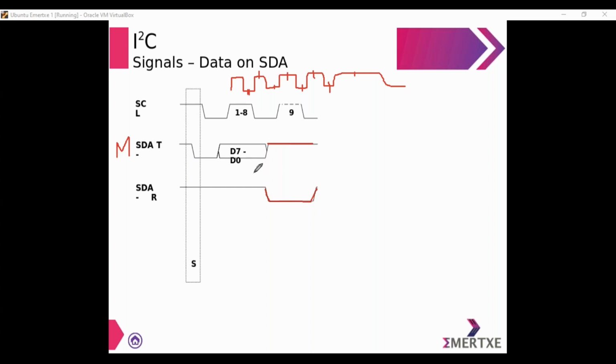Now RTC is done receiving the address of the second register. Now RTC should give the value in the second register. So now 8 more clock pulses get generated by the master. Now RTC is the transmitter and the master is the receiver. So RTC is transmitting, master is receiving. You can see the change: RTC is the transmitter here, and the slave is the receiver here.